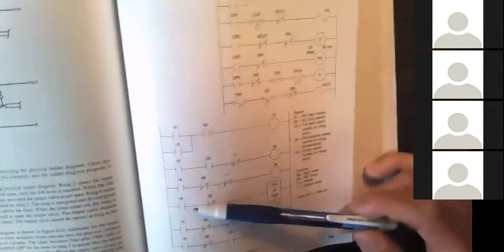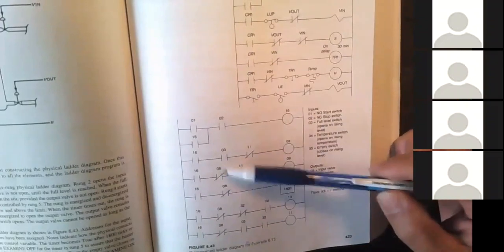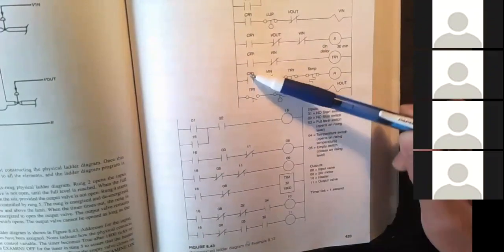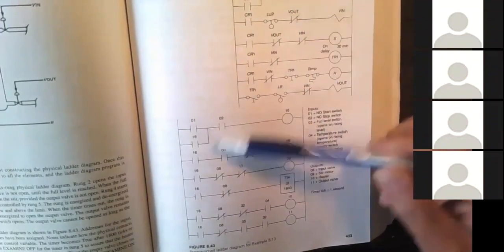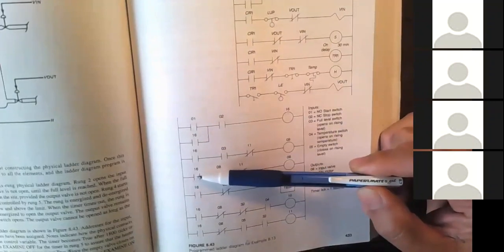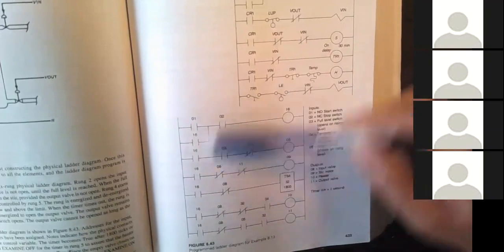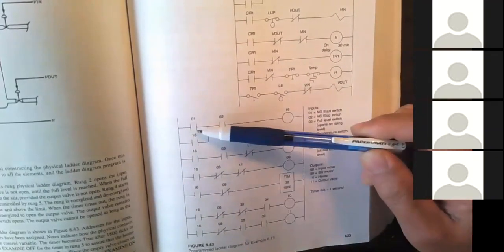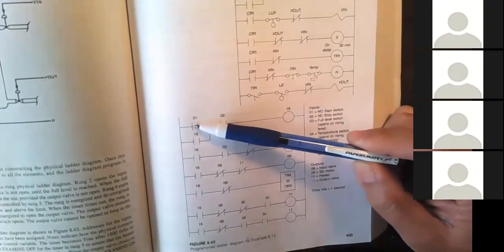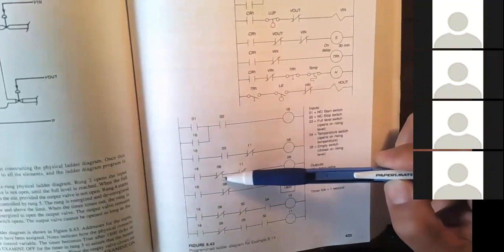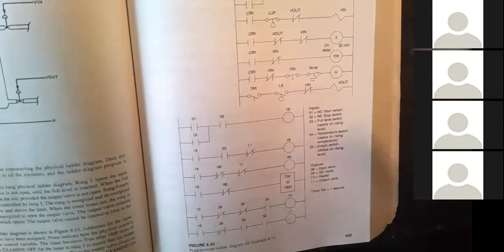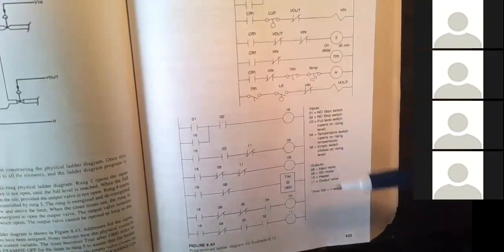By simplified, I mean go from here to here. All the sensors, all the push buttons, all the contacts are replaced just by inputs. So those are the inputs. They are normally open inputs and normally closed inputs. So there are just two kinds of inputs, normally open and normally closed.